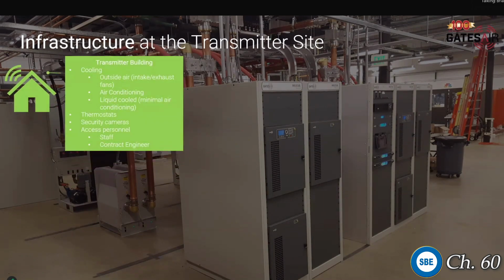So your transmitter building, some of the things that you want to know about the transmitter building is, how is it cooled? Is it taking outside air with intake fans and exhaust fans, or is it air conditioned, or are your transmitters liquid cooled and you still have a little bit of air conditioning? I was at a couple of mountaintop sites that are often in the clouds, and these sites would just simply take in and filter outside air and blow it through the room during the summer.